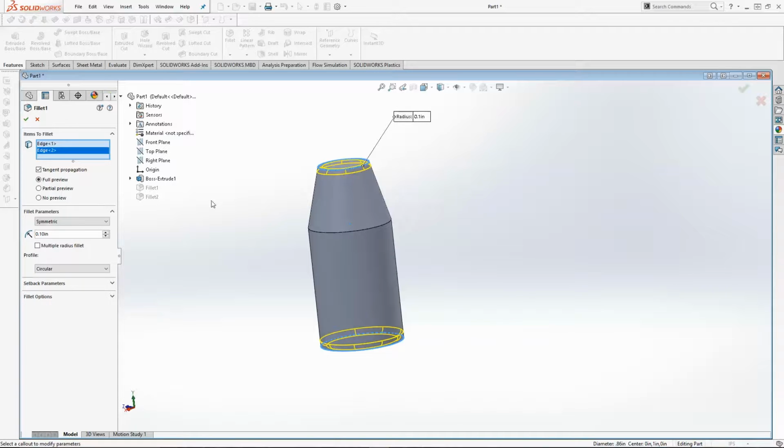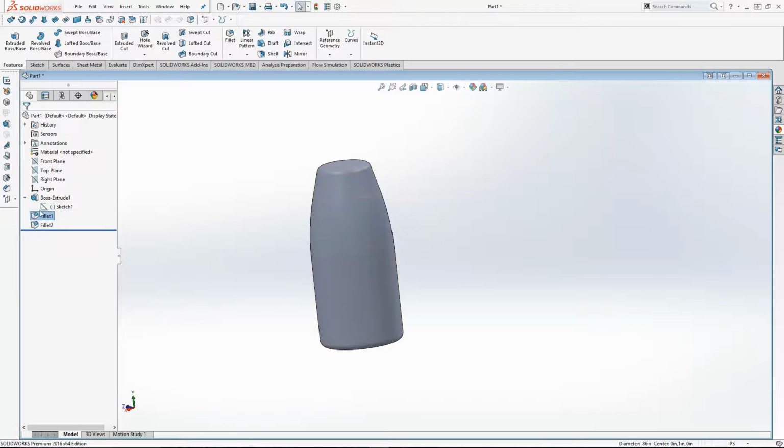And especially in parts you'll be creating, this is such a simple part, and I already have 3 features, and this is a super simple part for, not even including assembly. So generally you want the least amount of features as possible. If I made 2 separate features for these 2 fillets, then I already have 4 features.